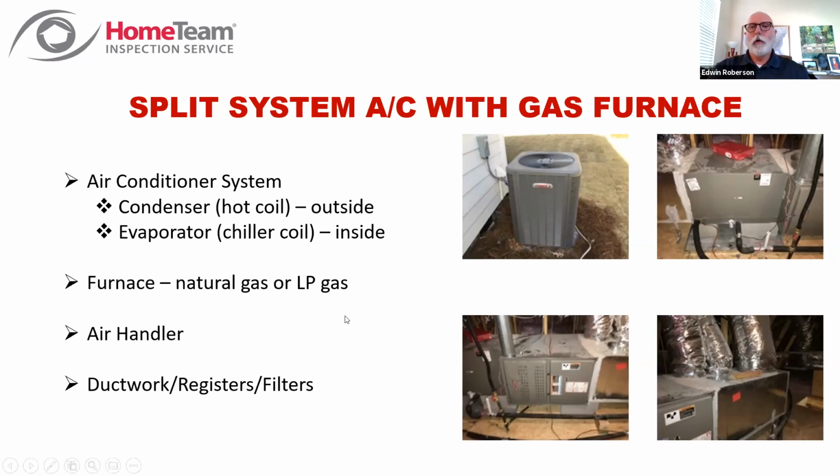And then in this picture, actually, the top and the bottom left really kind of show you everything, because the top is the outdoor coil. If you look over here on the left in that bottom left picture, that's the evaporator. You see the whole evaporator. Well, that's where the refrigerant line is going back and forth and doing its job. And then in this section is the furnace, the gas furnace. And then in this section is the air handler.